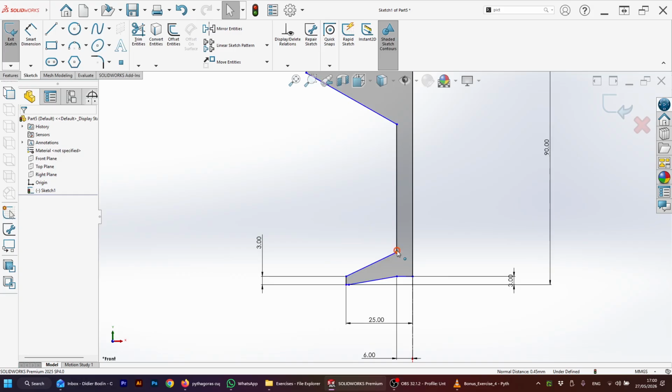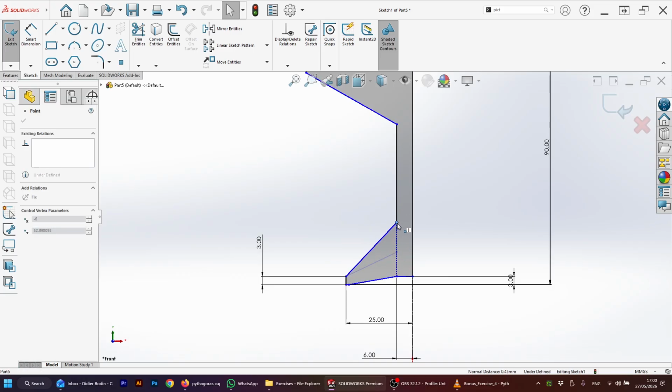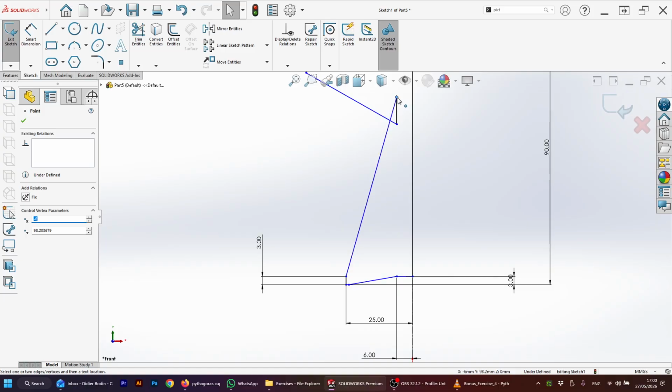If you want this, we can still define it, so this is going to be part of the free details in the design. If you want it to be thick, you can even put it like that, but don't cross. You see what he's doing? If it crosses, you have a shape within a shape. He's telling you this is wrong. That's why it turns from dark to white. If it's white, it means you have something wrong with your sketch. If it's dark gray, it means your sketch is correct.